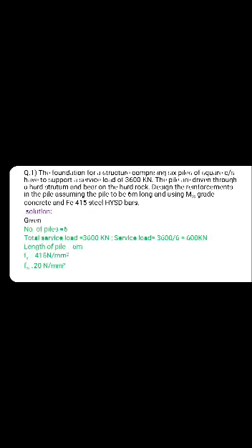First question. The foundation for a structure comprising 6 piles of square cross section has to support a service load of 3600 kN. The piles are driven through a hard stratum and bear on hard rock. Design the reinforcement in the pile, assuming the pile to be 6 meters long and using M20 grade concrete and Fe415 steel HYSD bars. The given details are: number of piles 6, total service load is equal to 3600.